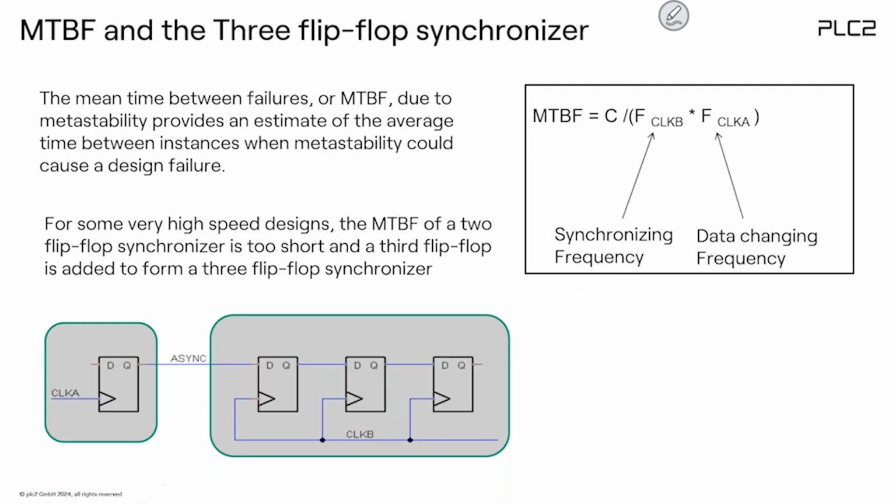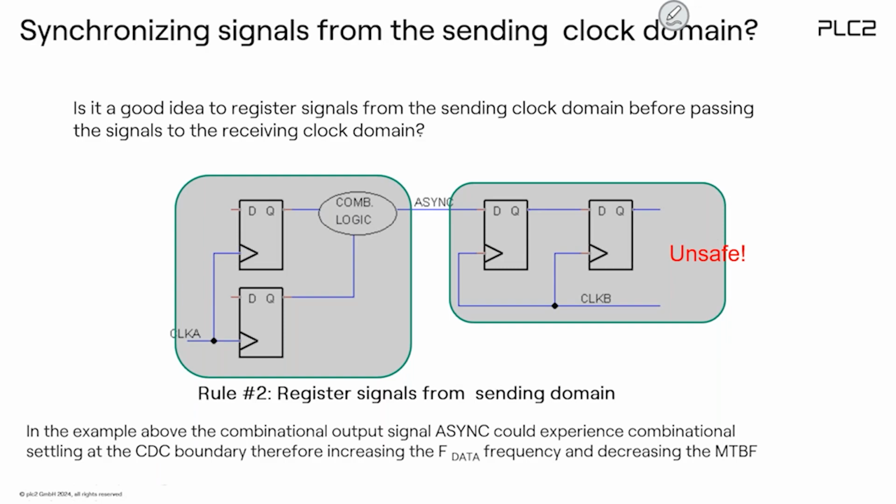But this is also supported by Vivado. You just define clock A, you define clock B, which I already did. Then you can ask for the MTBF. If this is not big enough, if I refer to our specification, and the customer asks for more security and safety, then you can add a third stage, and then you will get a new value.